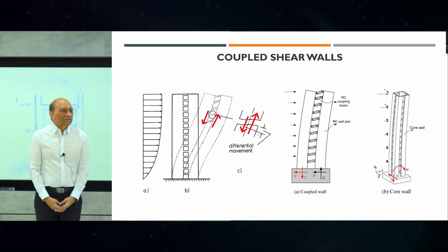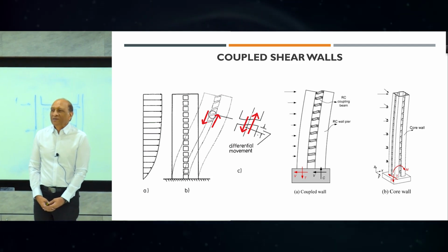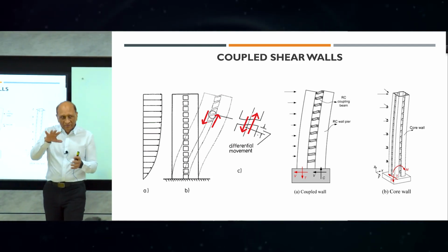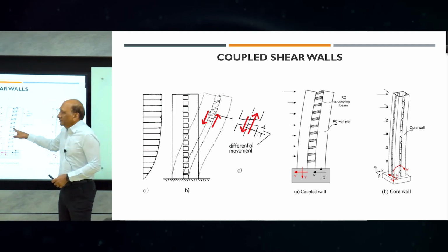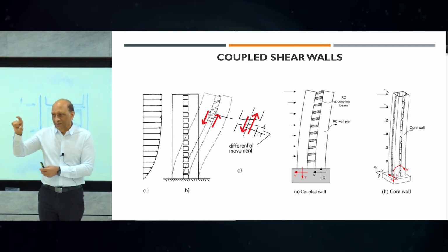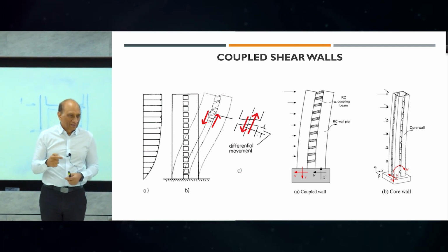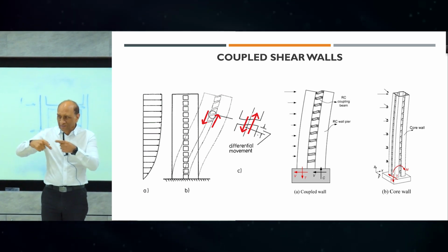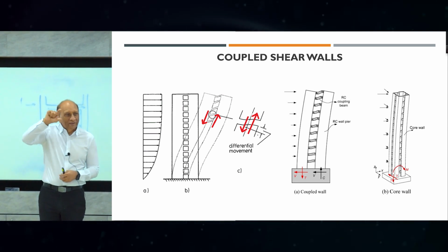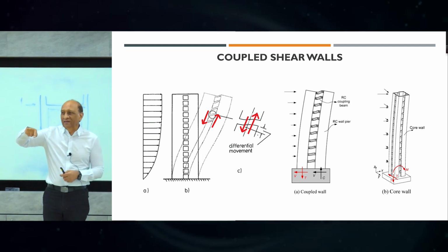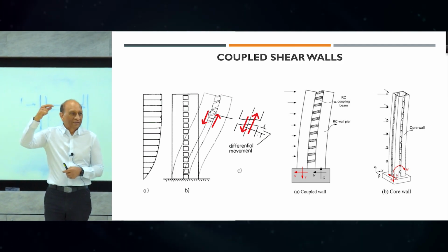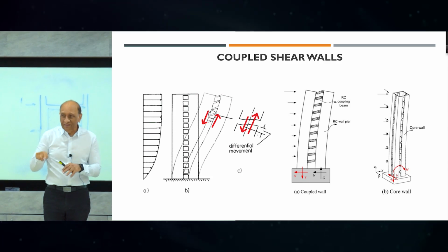We talked about ductility, we talked about capacity-based design, we talked about allowing it to yield. So the way to design, and we'll come to the detail, is that we limit their capacity to carry shear by limiting their moment capacity. We go the other way, backwards, because we don't want them to break in shear. To prevent that, we can limit their moment capacity, and from there backwards limit their shear capacity, because the moment capacity will not increase beyond a certain limit, and because the shear is created by moment, the shear is coming from moment.